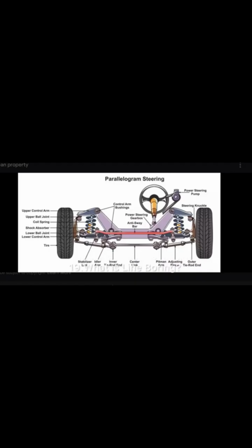19. What is line boring? Brings main bearing bores into alignment, fixes size, taper and out of round. 21. What is the purpose of cross-hatching a cylinder bore? Surface finish to retain lubrication film at the correct quantity.